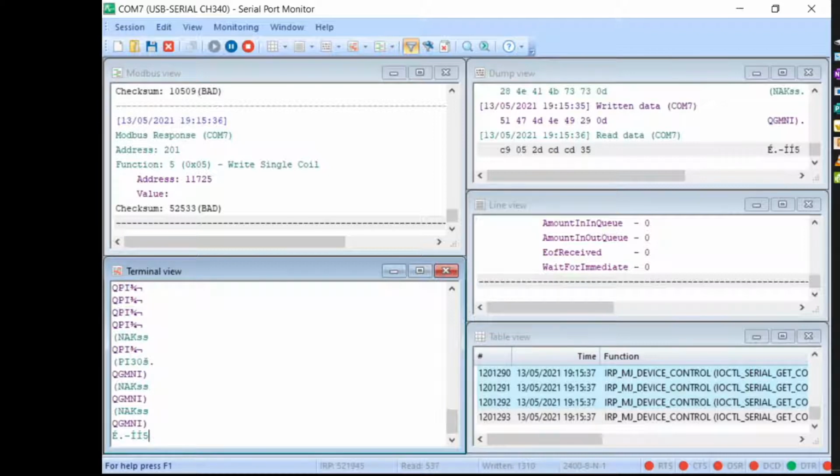This means that your hardware connection is good, your CRC is passed, and the PC and the inverter have started talking to each other. Though they are talking in different languages and don't understand each other, they are trying to communicate. Even this NAK is good for Arduino and inverter communication. When you receive this, it means that you are almost done.